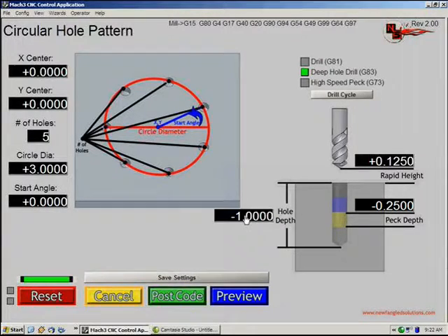And if you notice, this value right here is negative. In many of the newfangled machines, a negative value or a positive value for something like a hole depth, both of them are just as valid as the other. We did this because you could see how a depth could be assigned as negative or positive, because it's kind of like, yes, I want to move an inch down from here. So it could be negative, or you could say, yes, the depth is 1 inch. So if you'd like, you can type a positive or a negative value. I'm going to put in 0.75.